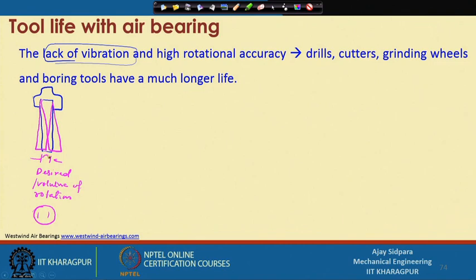So, this is the area where we actually want to focus. That means when you are drilling a hole, you are sure that whatever is the diameter of this is the diameter of the hole which you are going to drill. But when you are getting vibration here, what is going to happen? Your actual diameter is now this much, and that is also sometimes not feasible, because at the end, when you are going down and down with such a vibration, your tool will be broken.